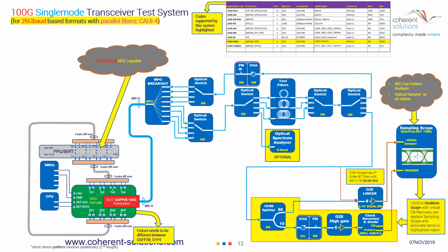In our very first setup, we saw 10 parallel signals with multimode fiber, each carrying 10 gigabit. In this case, what we're looking at here is known as a PSM4. This means that there's literally 4 parallel transmit signals, each one running at 25 gigabit. Because they have their own fibers, it does not need to be multiplexed.